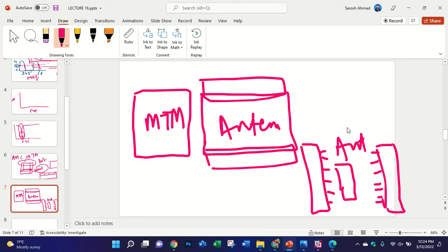It depends, of course, on the pattern of the antenna. If you want to enhance the pattern above the antenna, for that you need to put the metamaterial above. Or maybe if you want to use the side loops. In most of the cases we place the metamaterial in back of the antenna or inside the substrate of the antenna, like an EBG structure. So that's why there are many ways to simulate the unit cell.